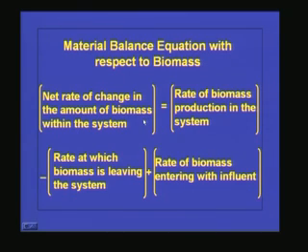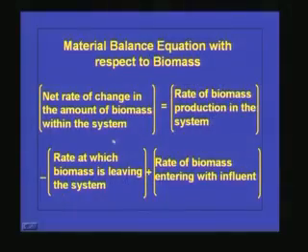Now we can see how we can find out theta c. If we know the theta c we can provide, and what the influent BOD and effluent BOD required are, because we know what treatment is required, it should meet the discharge standard. In terms of BOD it is 30 milligrams per liter. If you want to find out the volume of the tank, how can we go around it? We will make the material balance equation with respect to biomass.